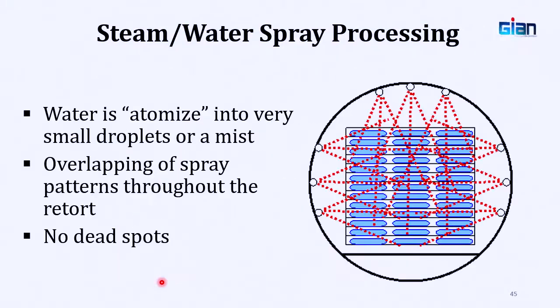So basically that system, rather than using a vessel which is filled with saturated steam, or filled with an air-steam mixture, or completely filled with water, in this case not completely filled, is like a cascade system, a water cascade system. You are just throwing hot water into it. In this case you have hot water as well as the steam together. So this is the example, steam and water spray. So you are atomizing this, you are throwing it from nozzles all around.